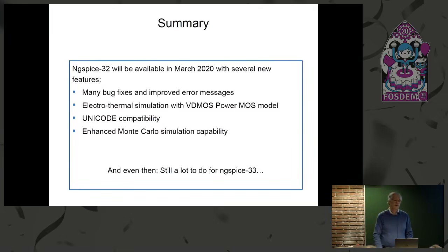Well, there is a polynomial function capability in ngspice, as has been in the old Spice 2. It's the same feature, same function. This is working. If you ask whether it's fully compatible, well, we are never fully compatible. The main reason is we don't know what LTSpice has in. We don't know the equations of LTSpice. So we can just figure out what should be similar, and this is what we are doing, and this is continuously improving.